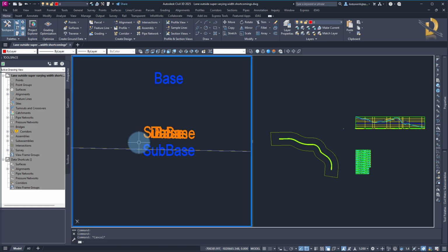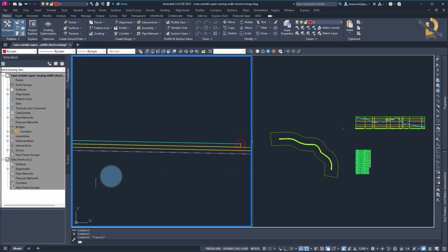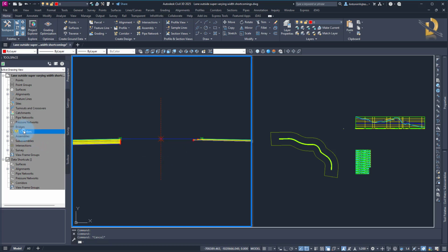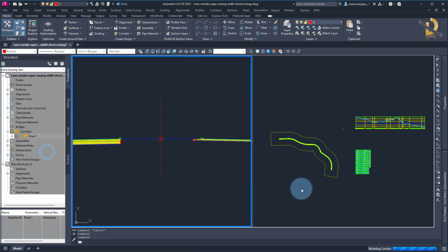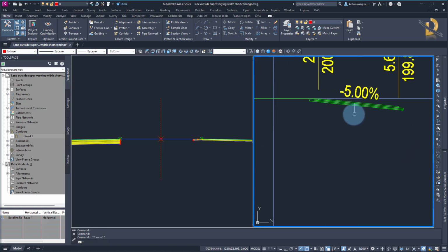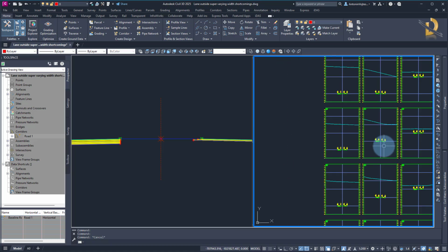Although it might not harm your quantities or anything, it can harm the performance because let's say 20 links are created in a corridor for no reason on top of each other. And let's look at the shift width, and that seems good. I didn't specify it probably for the third layer. Let's rebuild the corridor and let's see how it looks in the cross sections. Let's go there, and this is the result. It looks good. So this subassembly is useful if you don't have more than 4 layers. If you do have more than 4 layers, then I wouldn't suggest using it.